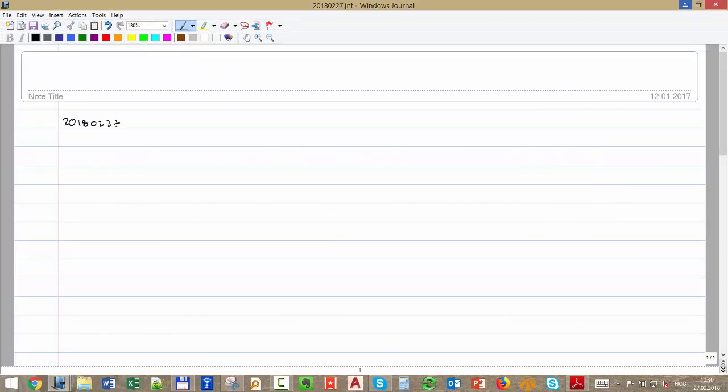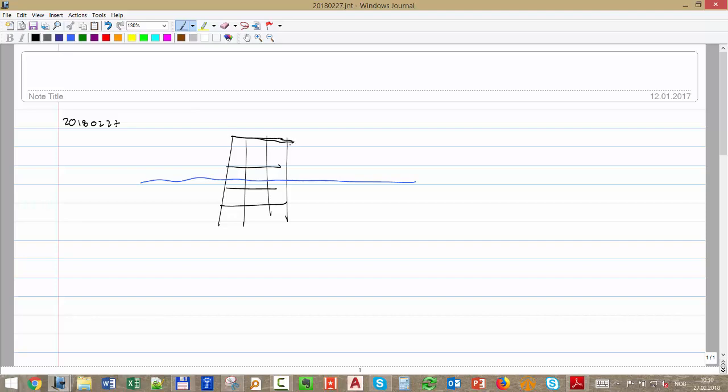Let's paste that into the notes of yesterday. Especially this 100-year wave, it's not important for floating structures, but for bottom supported structures, because if the sea level is here and you're expecting a wave, and here you have the lower deck, and you're expecting a wave that will actually be higher than that deck, then you will have a lot of damage done to what is on the topside. So you have to make your design such that it's higher.